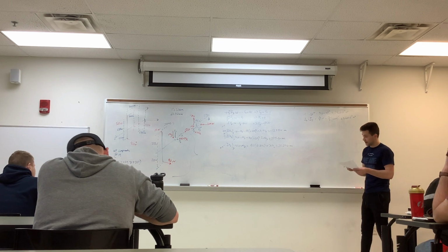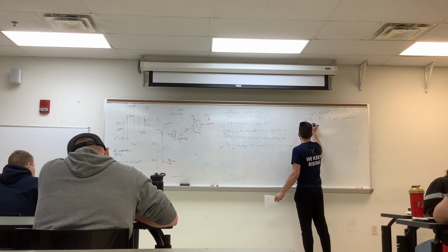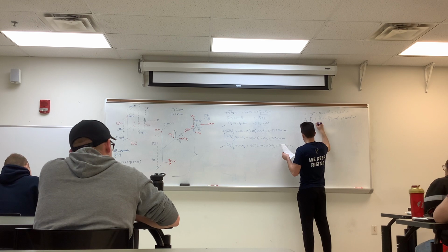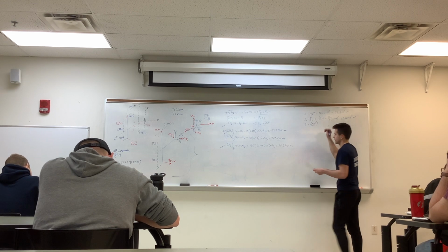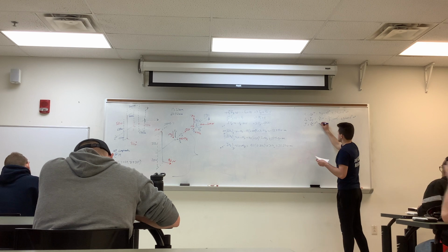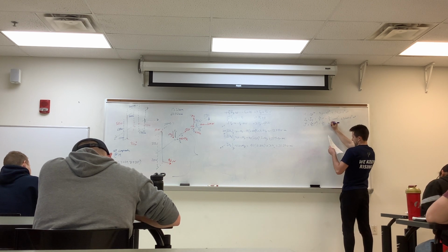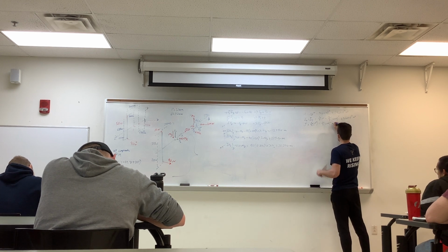Then lastly, our J, since it is a circular cross section, is equal to pi over 2 r to the 4th, since it's a solid circular cross section. And all this turns out to be is pi over 2 multiplied by that radius again, 0.025, to the 4th.